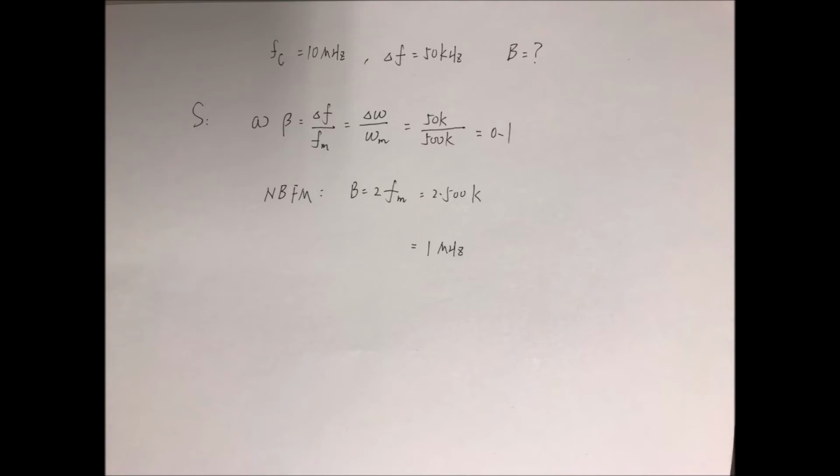So what is the 0.1 that we calculated? Yes, 0.1 is the modulation index beta, which is delta F over Fm. But we don't use it in the bandwidth calculation here; later we use it. Okay. So beta actually has two roles. One, it tells us which equation to use. Second, it can also be used to calculate your bandwidth for large beta and Carson's rule.